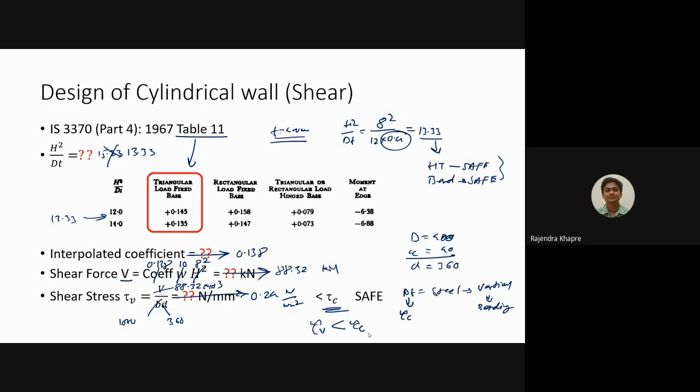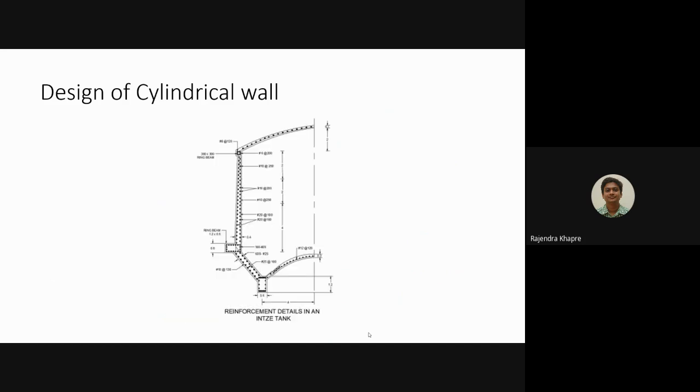Finally, you have to draw a very perfect figure for this. Remember, we have taken the thickness as 400 mm. Since the height is 8 meters, we can provide a section where the thickness here is 400 mm, reduced up to 200 mm at the top.